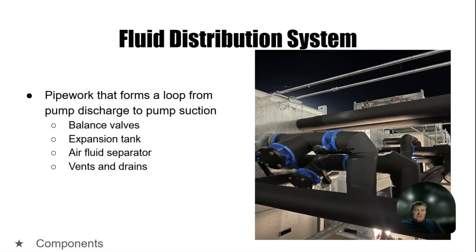When we're doing this, we're using ACR copper. It's slightly pressurized with nitrogen and has rubber caps on the end. We don't have to use it. It's not part of the spec, but it keeps the system free of contaminants.